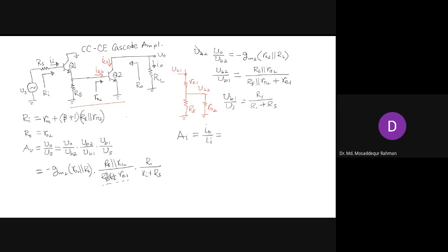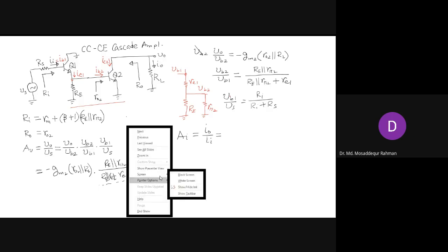So that is our base current for Q2, IB2. Then the current that is flowing here is our emitter current for Q1, IE1. And then we have here I, which is the same as IB1. So this is how we break it down, and now we have assigned the currents.